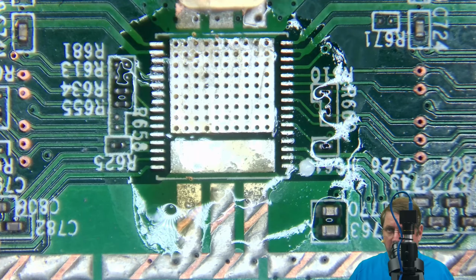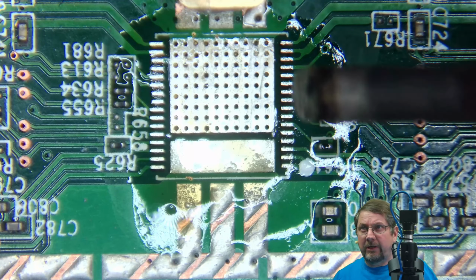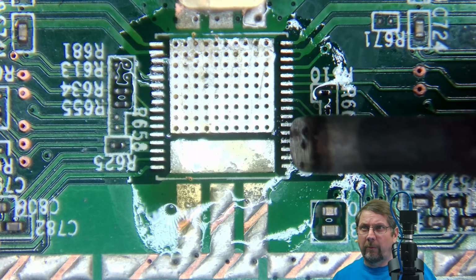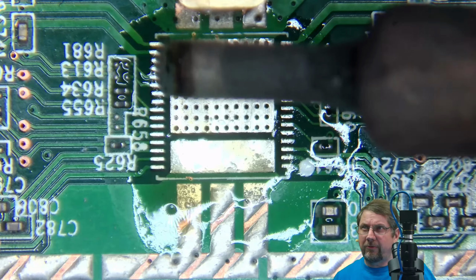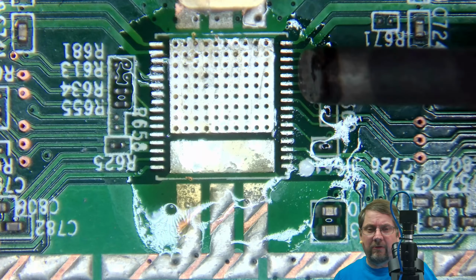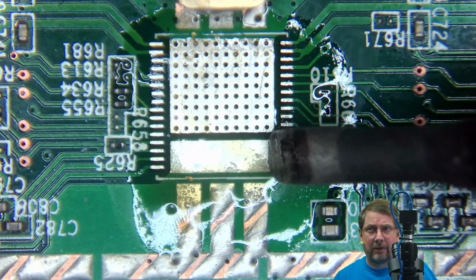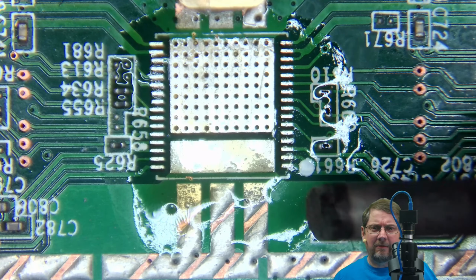All right, just a quick public service announcement, if you will. When you're desoldering these little bitty pads, remember not to put much pressure on them, because if you put very much pressure on these little bitty pads, you'll damage the solder mask. And if you like doing solder mask repair, press as hard as you want, but really the heat does all the work.